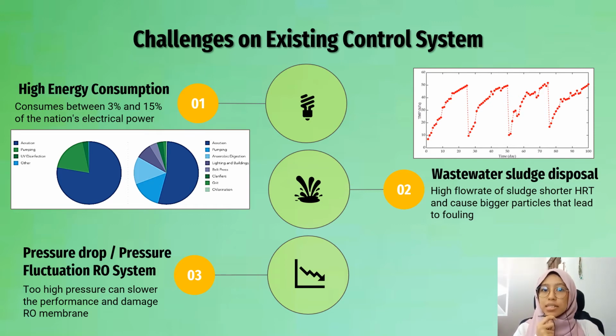The last challenge is pressure drop or pressure of the system. Around 4 to 5 psi per element is considered a normal pressure drop value for a commercial RO membrane during its usual operation. Delta P will not change if temperature and flow rate are kept constant.